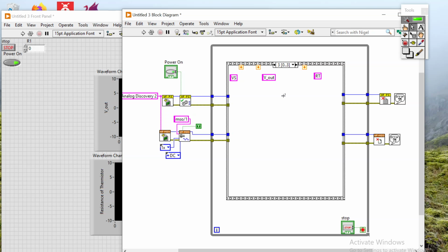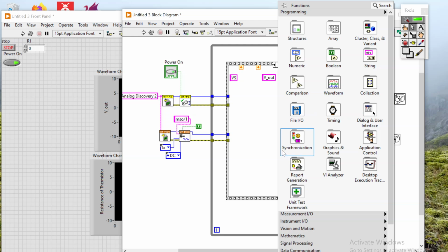So what you want to do is, in Excel or MATLAB or Python, create a column of X's, which would be your resistance values, and a column of Y's, which would be your temperatures, right? And then you want to do a fit, so a linear fit. So you want to come up with an equation, remember y equals mx plus b, for that data. And in that case, your y is going to be temperature, and your x is going to be the resistance of the thermistor.